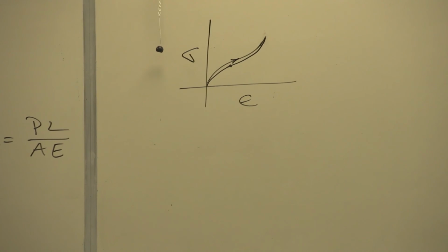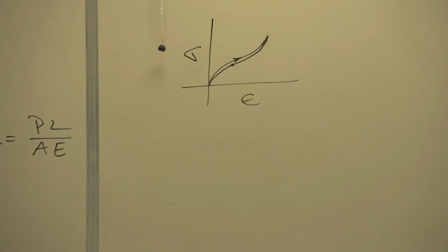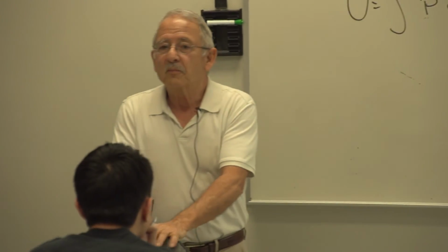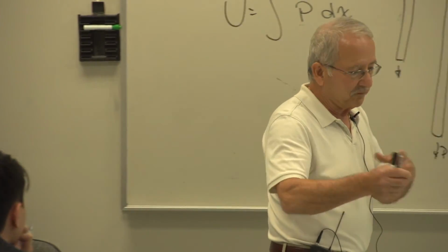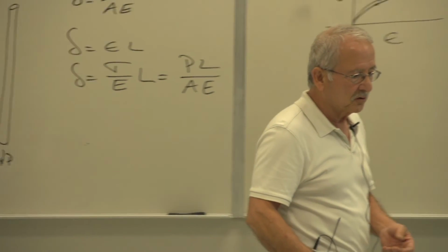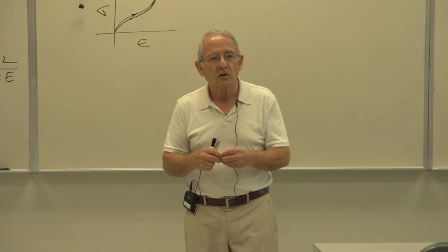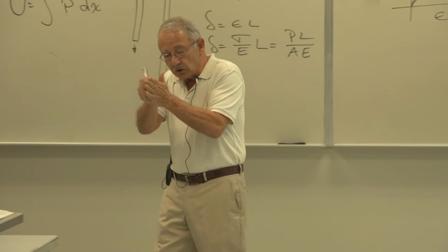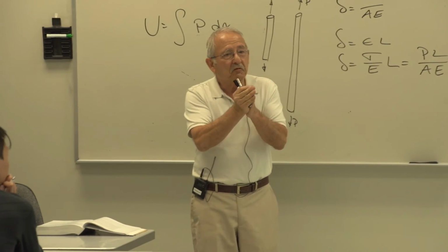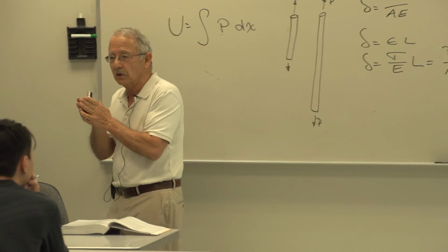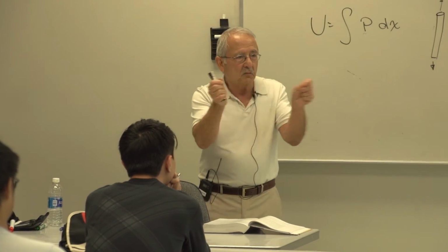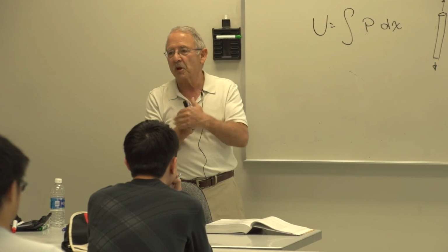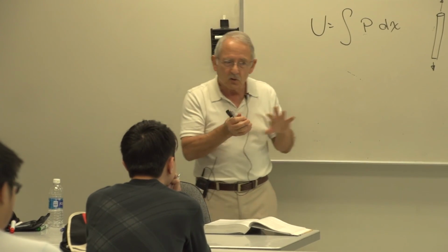Where does it go? Heat. Rubber is made of very long, not that this is a part of stress analysis, but it's good for you to know, it's made of very long chain molecules. When you stretch it, these molecules rub against one another, create friction, which creates heat. You can test this very easily. Take a rubber band, load it and unload it about 5 to 10 times, and put it to your face. You will feel the warmth. The rubber warms up. That's due to that lost energy. Okay, so it's a little bit about this.